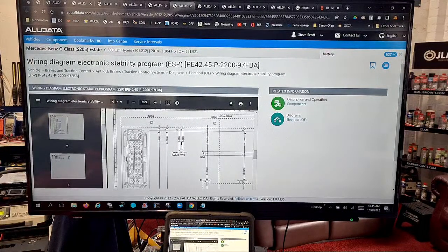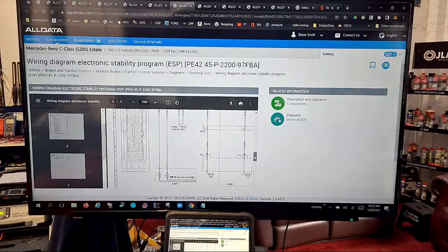Yeah, so I've actually confirmed it, T-Bag. So the brake pedal is hard, and the auxiliary battery warning is on, and there's some sort of load shedding going on. So you can see there with the Mercedes wiring diagram, we've got a pinout for the ABS, and that gives us our powers and our grounds, so we can check our powers and grounds.